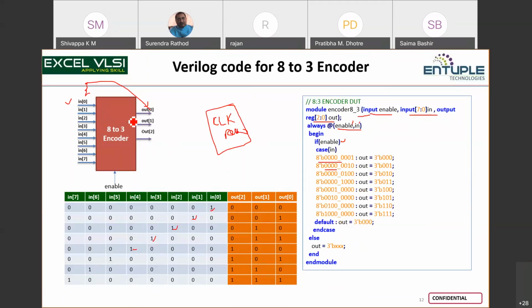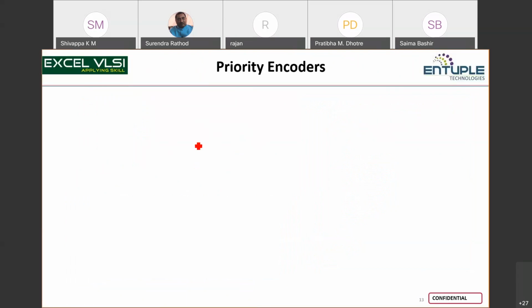In combinational circuits, it is just the logic design, the output depends on inputs, and whatever inputs map to this encoder, the gate structure is what is involved. Apart from that, there is no clocking. The default case also is defined here, and if it is not enabled, the output you give is XX, unknown. So you can model the encoder like this.